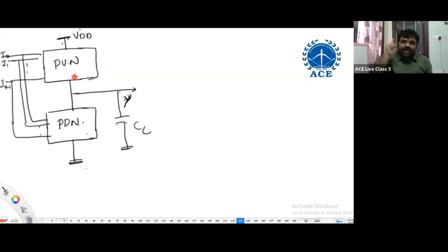One is an N-channel MOSFET, the other is a P-channel MOSFET. If one is on, the other will be off when you apply the same input. Obviously one is on, the other will be off. That means these two are complementary switches. After taking the dual, complementing each literal gives the complement of a function. That is how we make these two networks mutually exclusive.